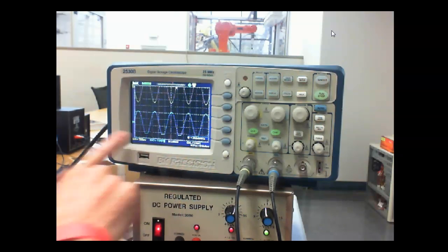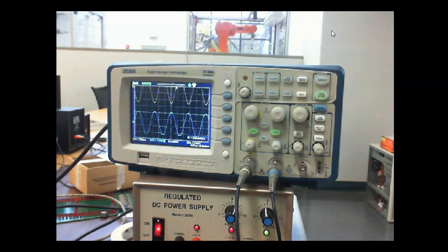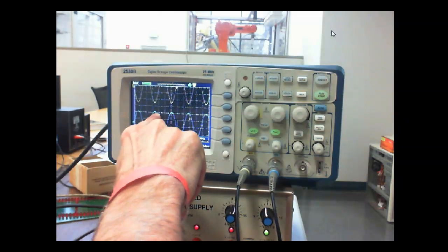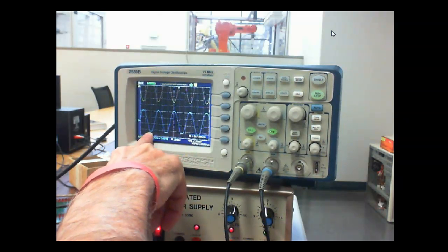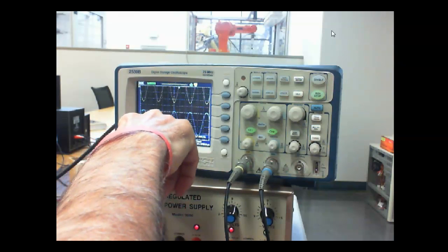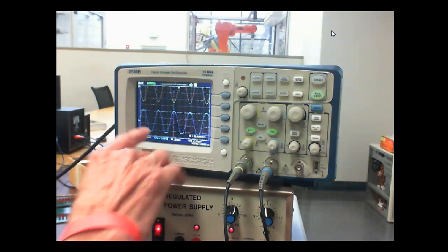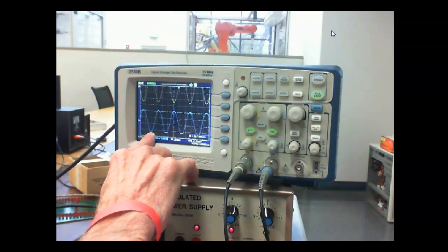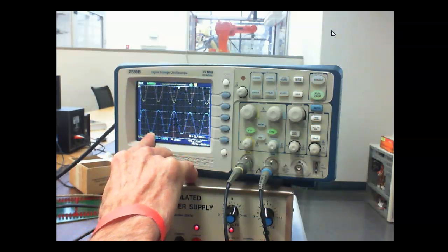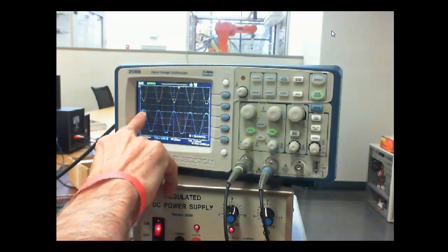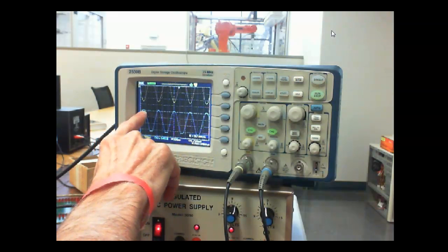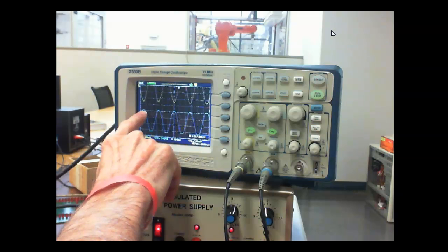So what I'm doing is my input is big enough. I'm sorry, up here it's cut off, down here it's saturated. Did I say that right? So here on the output voltage, it's opposite of the input. If it drops 20 volts, that means it's cut off. If it drops 0 volts, that means it's saturated. So this means I'm inputting this thing enough to saturate. If it's clipped on the top, that means it's cutting off, right?